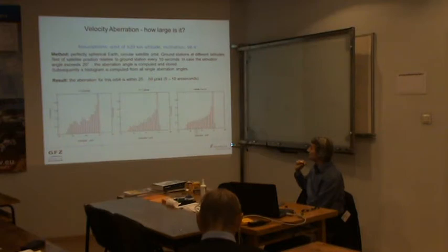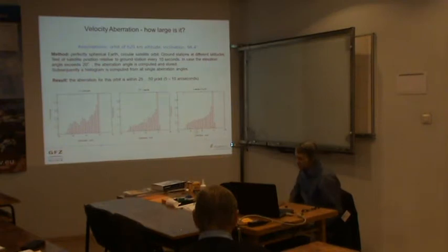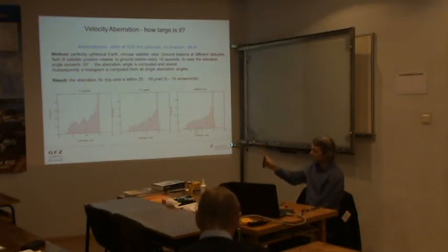That means you can even choose your orbit in a way that the satellite is permanently flying along the border between light and shadow, permanently along the dusk-dawn line, as we call it. This is very nice for satellites which have a large demand in power, for instance radar transmitting satellites. They all continuously put their solar arrays towards the sun in such an orbit at around 98 degrees, practically never go into the eclipse of the Earth caused by different seasons.